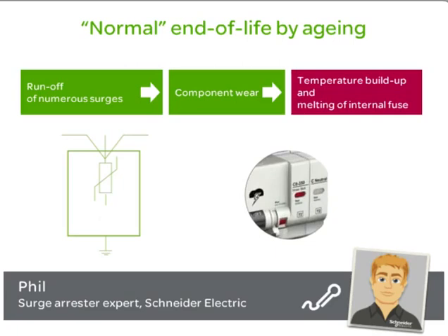An operating indicator, which is white when the surge arrestor is in operation, turns red at the end of life, indicating that the surge arrestor must be replaced, since the installation is no longer protected against overvoltage.